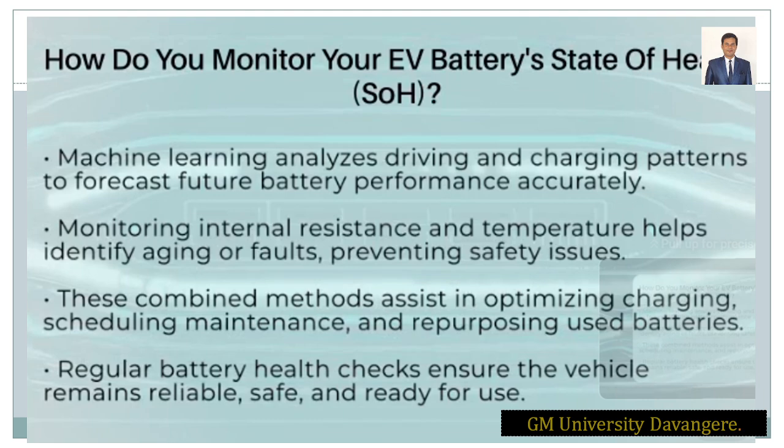So the BMS will try to calculate the actual condition of the batteries by collecting various parameters. It will try to see what is happening inside the batteries. It will check the internal battery models, and use various sensors which can sense parameters such as voltage, current, and temperature. It samples each cell every 100 milliseconds.